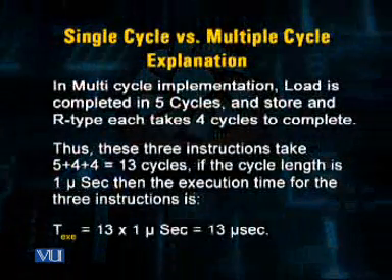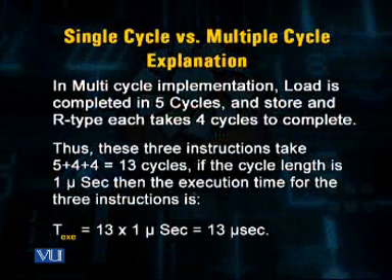Whereas in case of multi-cycle data path design, the load instruction can be executed in 5 steps. Store instruction is executed in 4 steps, and register type add instruction is executed in 4 steps. Therefore, it requires a total of 13 microseconds to completely execute this small program.